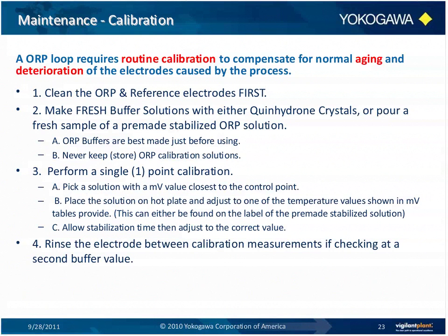However, it's common for two buffer solutions to be used, one to do the calibration and one that's just used as a check. It's always recommended to use fresh buffer solutions to avoid the possibility of introducing errors from contaminated or aged solutions. And you also need to note that, just like your pH buffers, these liquid solutions have a limited shelf life and should be used within that time frame.